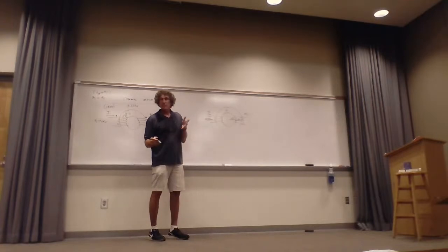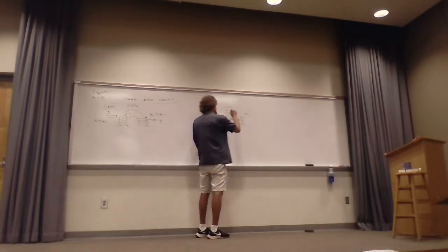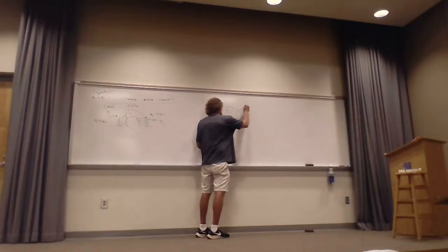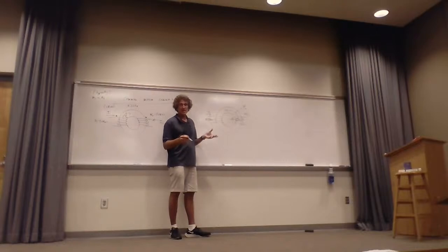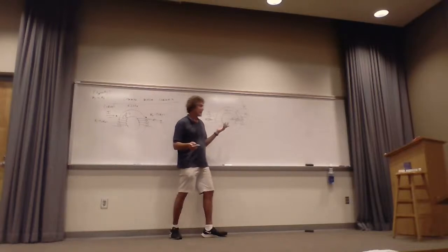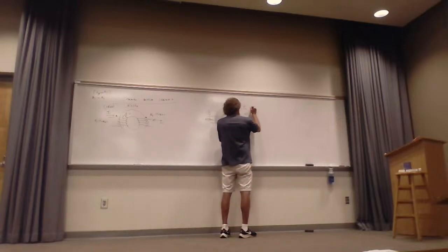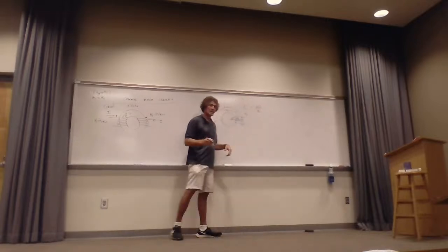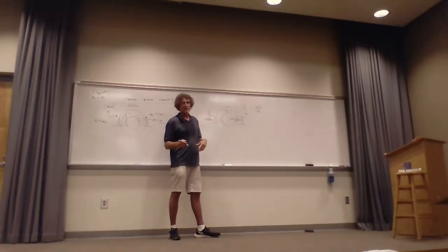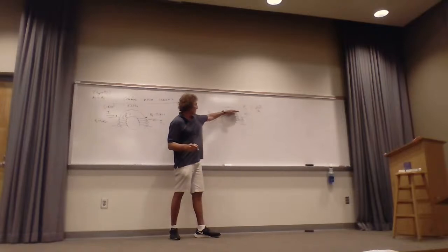Now, if you want the mutual inductance, you find the flux that's going through the secondary coils caused by the primary coils. That's equal to N1 times I over the reluctance. Then you multiply by the number of coils it goes through.